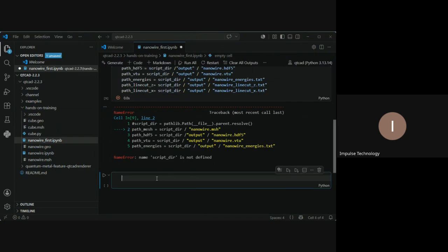After that, we have to change the device structure to nanometer. Like here, you can see the mesh structure in the normal unit. We have to convert it into nanometer. For that, we have to give the scaling here. Like scaling, and after that we have to assign the mesh here.